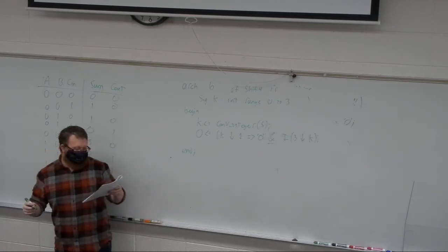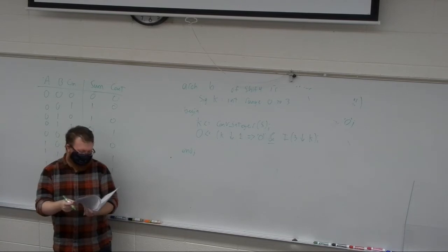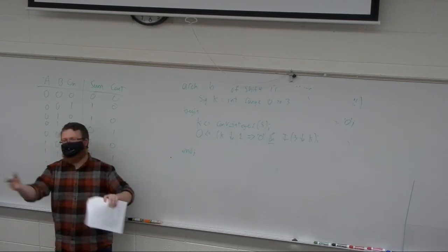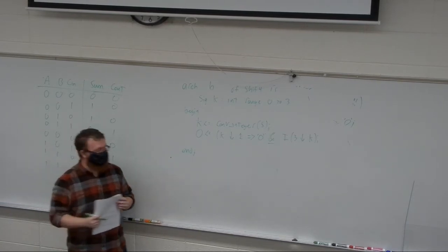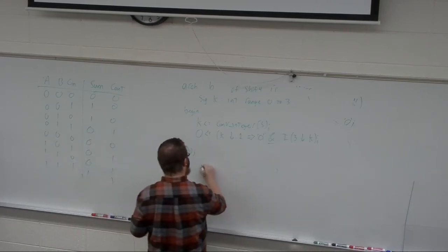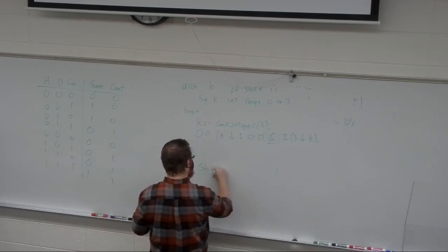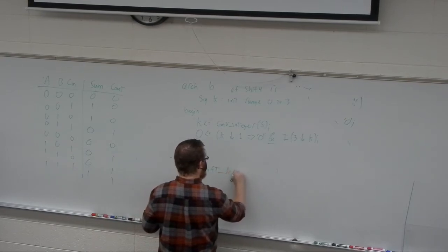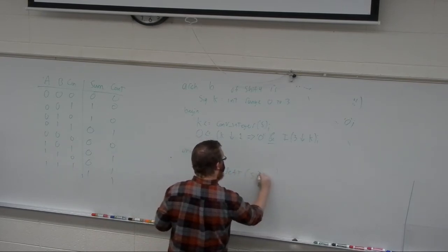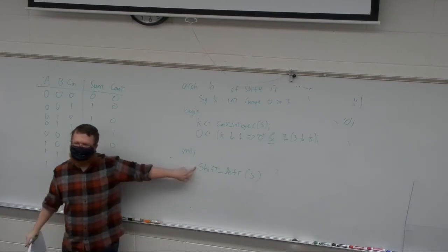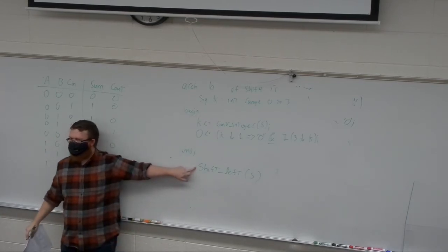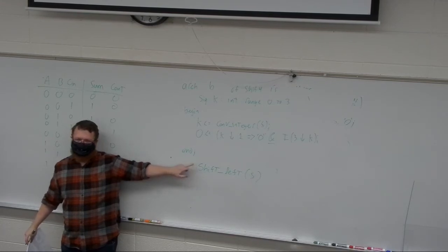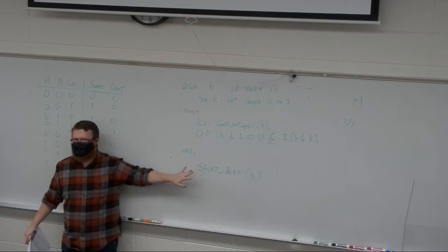You'll also notice, I don't know if the book tells you this, as long as you import the correct libraries, you can just do this. Shift left, shift right. Those are viable commands with the unsigned and signed libraries. And I think numeric standard.